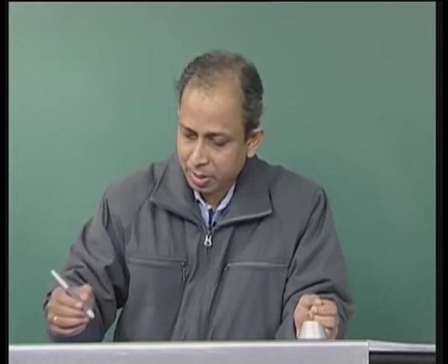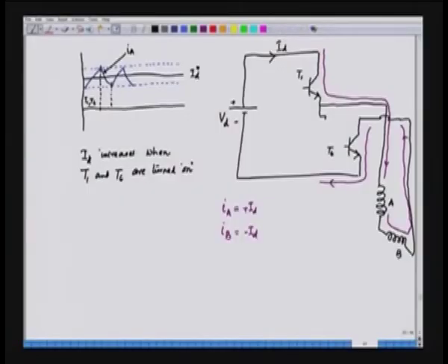The diodes are present here also. So, we have the diodes here, and this is the feedback diode for the other transistors which is not controlled here. So, this is D4, and we have another feedback diode which is present here, which is D3. So, when the transistors are turned off, the current direction should be maintained. So, we will maintain the current direction. So, this path is not there.